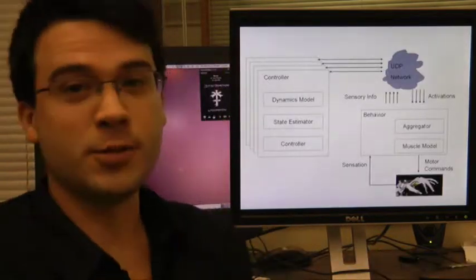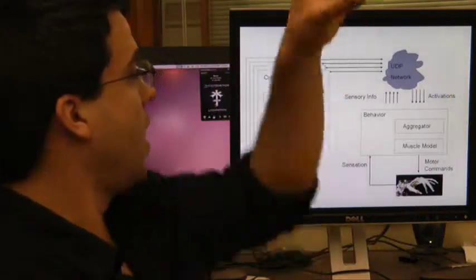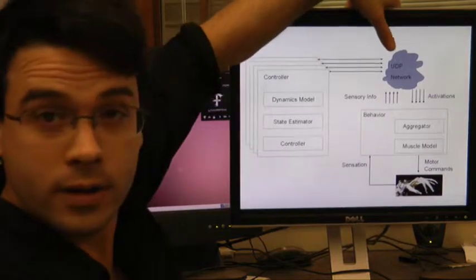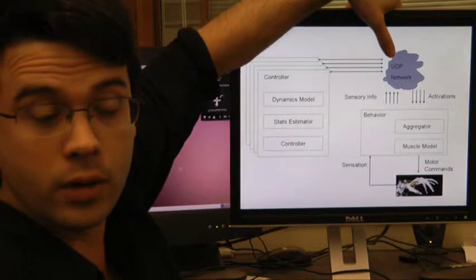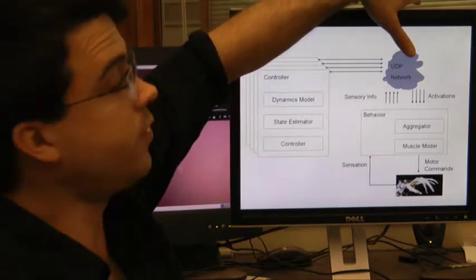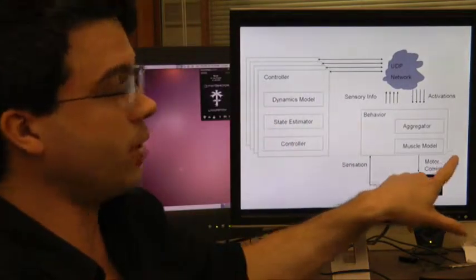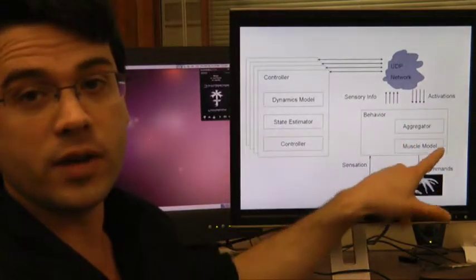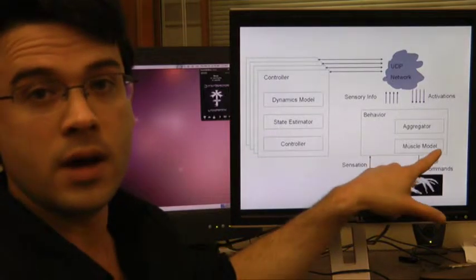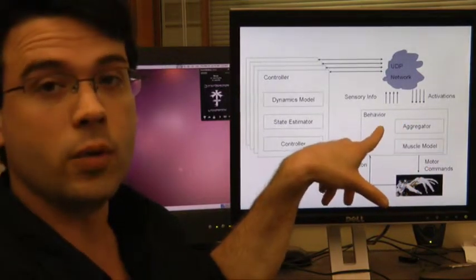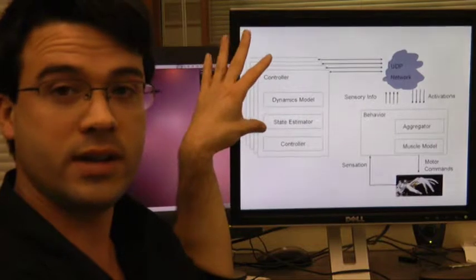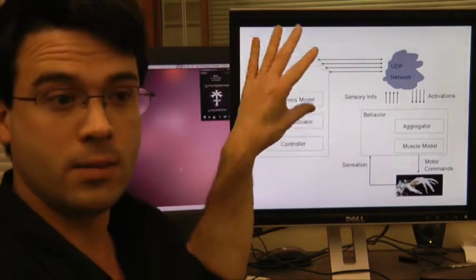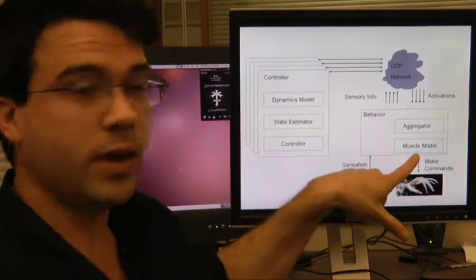Okay, this is what comes out. You want controllers that are decoupled from the system through a network, and that network will interface them with a really rapidly running, and therefore stable, robot controller, a behavior that goes really fast, like 200 hertz. The way that behavior will deal with the asynchronicity, heterogeneity, and remote slowness of the bank of controllers is by running a muscle model.